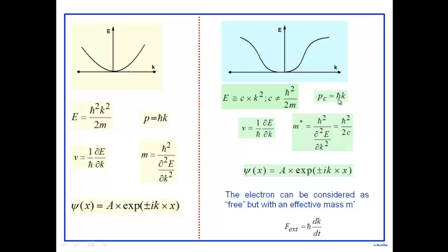So those forces are already there acting upon the electron, but all its effects I've taken into m star here, right? So now Pc equal to h bar k acts like a momentum, and when you apply an external force, this Pc here or h bar k changes in response to the external force, just like a free electron here. But don't confuse h bar k now as the total momentum of an electron. It is not. Okay, and that's why people sometimes add the phrase crystal momentum, because the electron is moving in a crystal. It's some effective momentum inside a crystal, to separate it from the fact that it's not the total momentum. This is only a model. We are modeling an electron as free, and therefore we are saying Pc is equal to h bar k, and all of this is valid here.